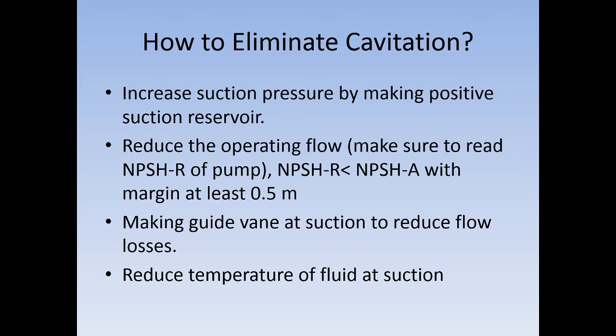So how to eliminate the cavitation? Of course, you have to increase the suction pressure. Second, you reduce the operating flow, and third, in the pump manufacturer's application, they usually have a guide vane for the high performance pump at the suction.